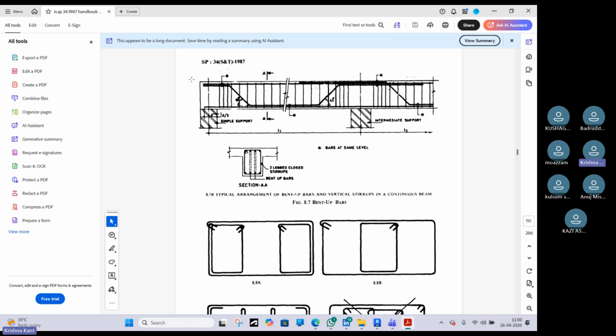Okay. And at the corners, the load is too heavy so that it will bend from the edge. So at that time also we need extra bar to support the top corner. So basically the concept is to provide extra bar on this corner and this corner joint, and at the center because of the extra load.